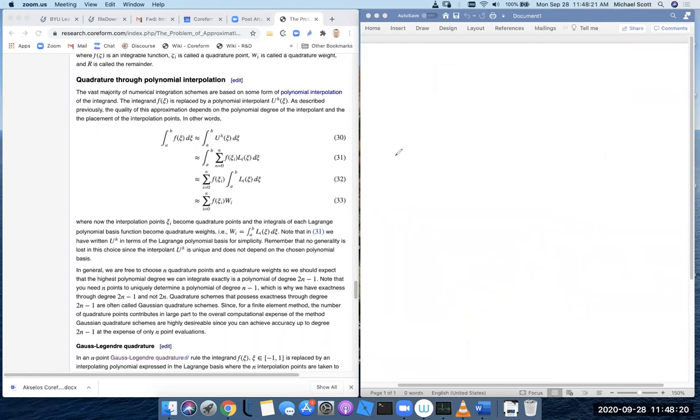Now, Mike, when you do reduced quadrature on a beam, that's not necessarily going to make you get the right solution. You have to use it correctly, right? There's a theory that guides the selection. But in general, you can't just use those reduced quadrature elements and suddenly use solid elements on a beam. Well, you have to be careful. Yeah, you have to know what you're doing. There's no free lunch. The point here is that quadrature, if you don't have this picture, is completely meaningless. If you don't understand what's going on underneath, it seems completely arbitrary what we're doing here.